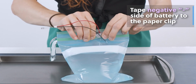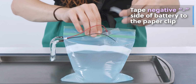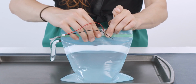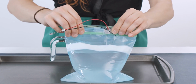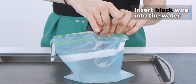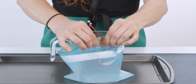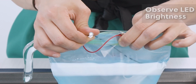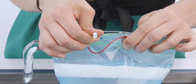Tape the negative side of the battery to the bag on top of the paperclip so that it rests snugly against the paperclip. Insert the black wire into the water so that the bare metal sits in the water but is not touching the paperclip. Then, check if the LED is on. Observe the brightness with different saltwater samples. The more salt that is in the water sample, the brighter the LED will be.